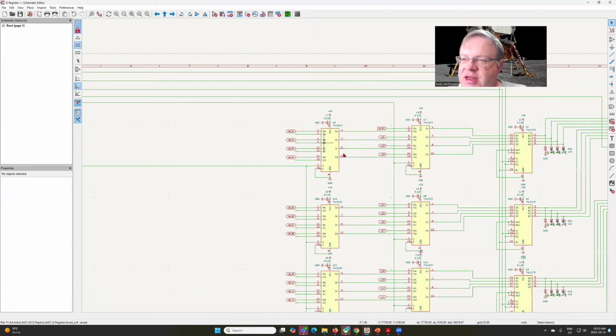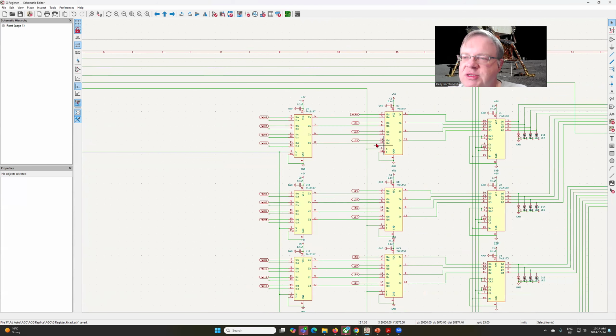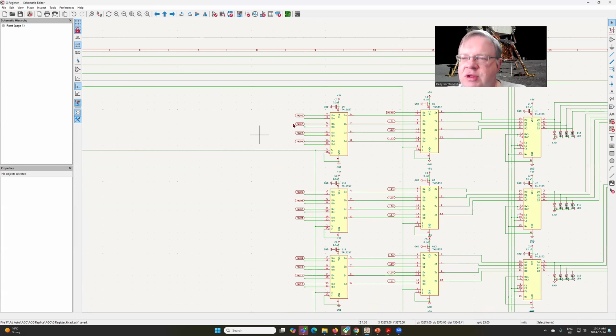If that's asserted and it goes low, we'll pull the selector low and load in the contents of the L register, based on that pattern that we saw within the PowerPoint. If not, then we'll go to this selector, and this is where we'll pull in the contents of the write lines. We can see the write line all the way down. Right now these are just hanging because we're still working on designing that editing logic, as well as where we will bring in the contents of memory when we want to load it from memory.